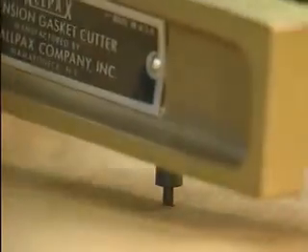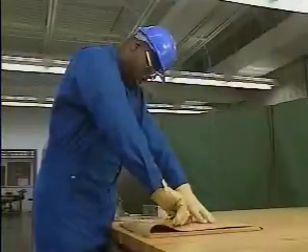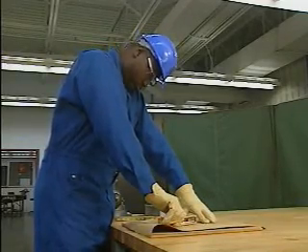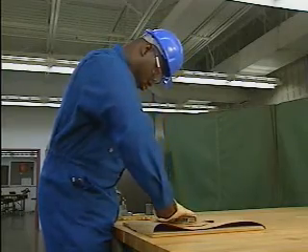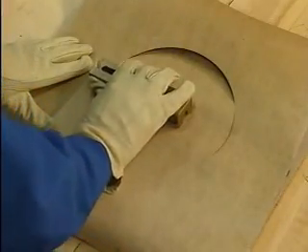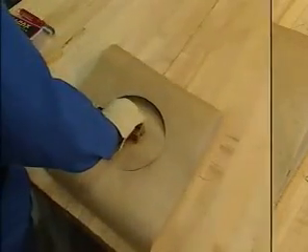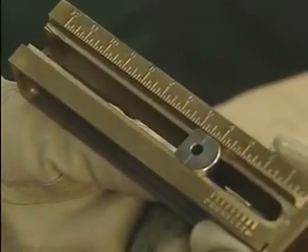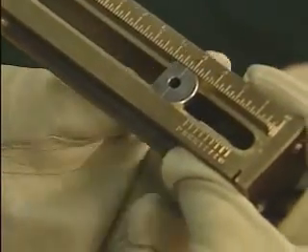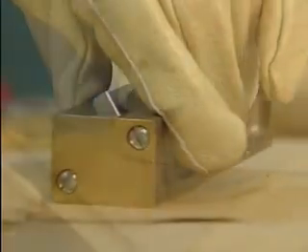The mechanic places the cutting tool on the pin and begins the cut by rotating the cutting tool. Once this cut has been made, the pin will still hold the gasket material in place so that the inside edge can be cut. When the cutting tool completes a full circle, the outside edge of the gasket has been cut. The mechanic then removes the cutting tool from the pin and readjusts the blade to the inside diameter measurement of the pipe flange. He places the cutting tool back on the pin and turns it one complete circle to cut the inside edge of the gasket.